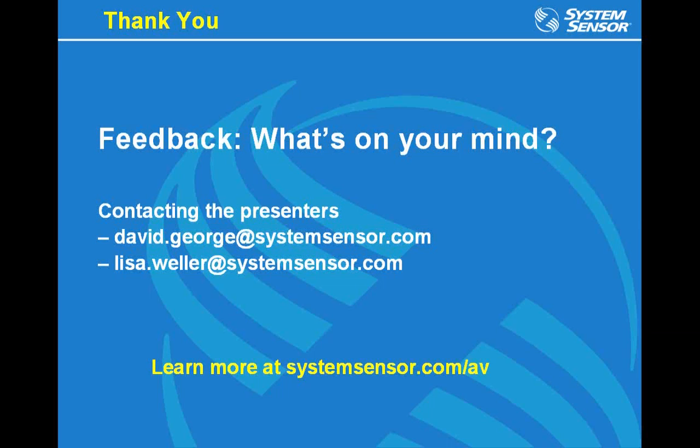It looks like we're at the last question, and then we'll go into the summary here. It was a question about reflective surfaces again. I think it's a follow-up to that one. Are fewer speakers with a higher setting better, or more speakers with a lower setting better in buildings that have a lot of reflective surfaces? Pretty much in any application where you're looking to meet a specific intelligibility score, more speakers at lower tap settings are always going to get you a better score as opposed to fewer with higher tap settings.